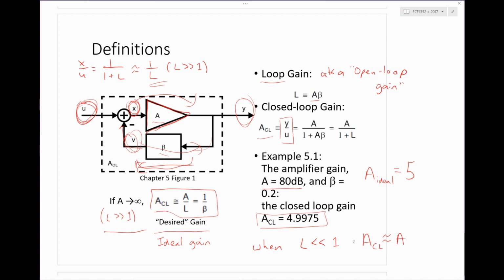I mean, for example, take any amplifier, just to illustrate the point. Just consider a really simple common source amplifier here, which could be the equivalent half circuit of a differential pair, which is a very simple op-amp, right? So even for this, the normal small signal analysis we do would say it's got a forward gain of gm times rds, and then it's got some frequency response, maybe that depends on the Miller effect or whatever. But in fact, if we somehow injected a test signal here, let's say there was some noise or some other circuit was operating over there,